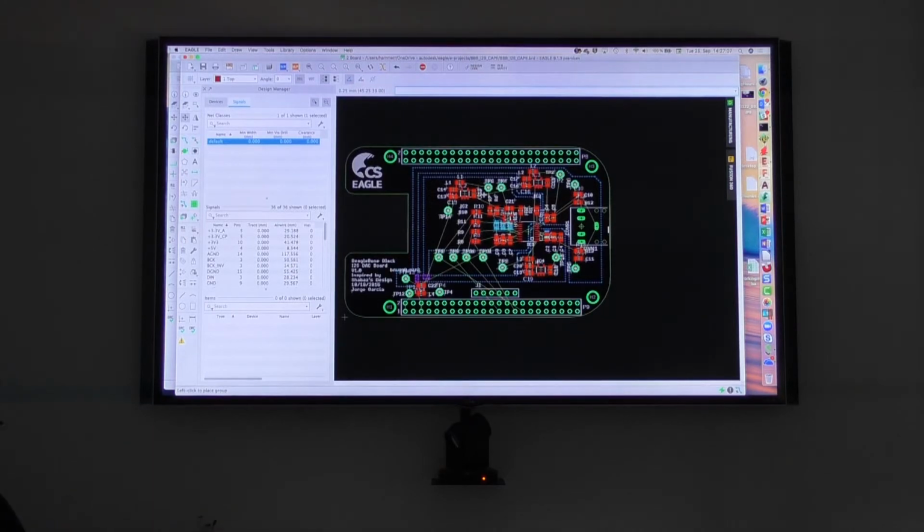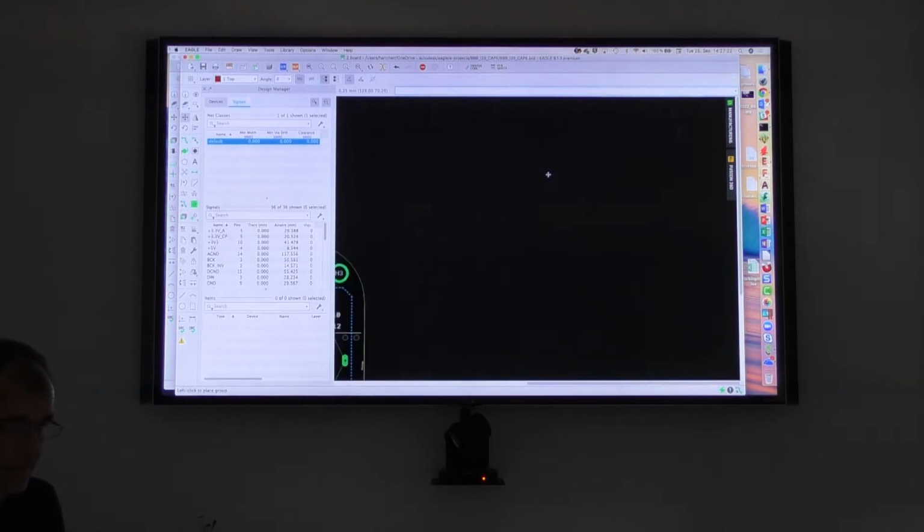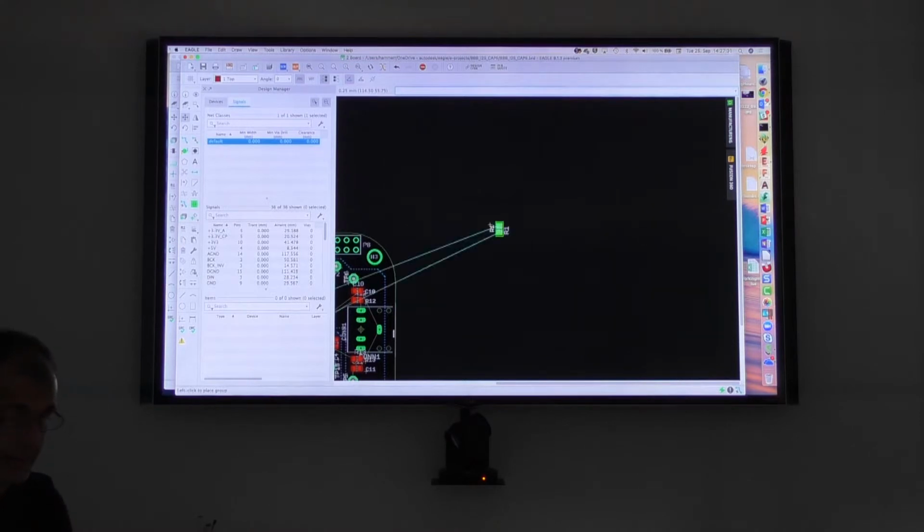And if I have a lot of components, it's tedious to zoom out, choose a component, click on it, go back into the board, place it. So even if I do not see a component, just let me show you, I have the move command active, and I want to move R1, the resistor number 1, I type R1, enter. What happens? The component jumps to my mouse.